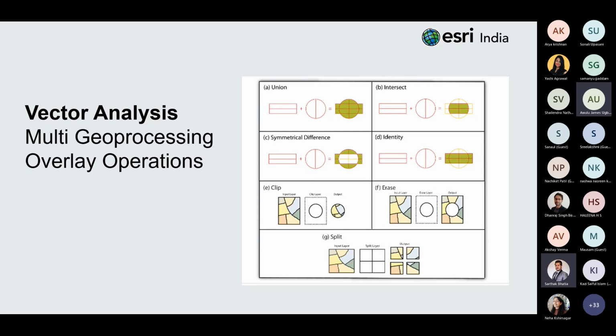For those who understand logical operators, it employs the simple OR operator, which means a union can be used when 2 polygons are used as input layers, and it will preserve all feature attributes, information and spatial extent, and give us a combination of the 2 polygons as output.